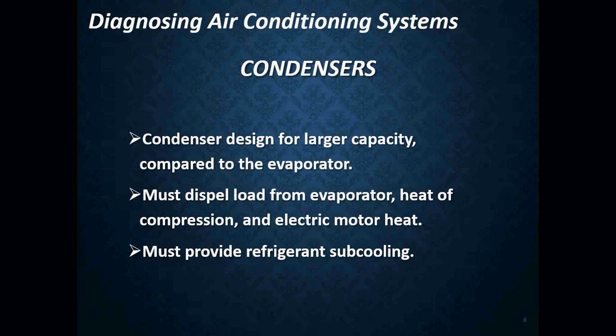Just like the evaporator, the surface area of the condenser affects the design temperature difference between the condenser temperatures and your ambient temperature. Ambient temperature is what the air is outside. The larger the condenser, the more expensive it is to manufacture. But the EER will be much higher. EER is basically the rating of the efficiency of that unit.